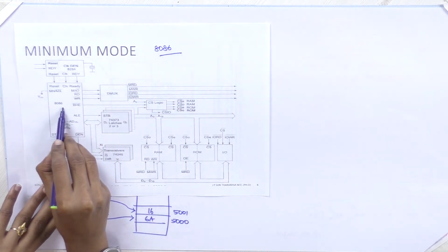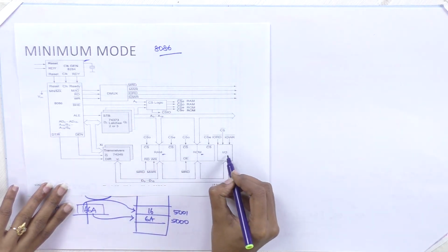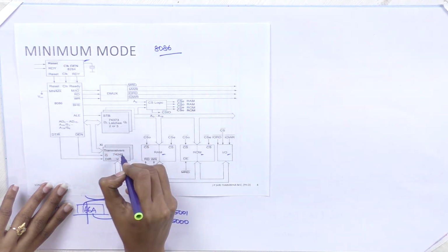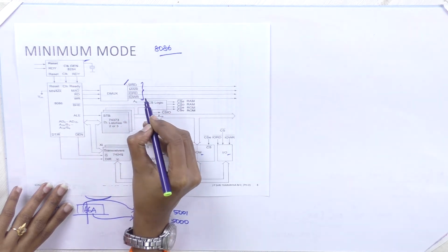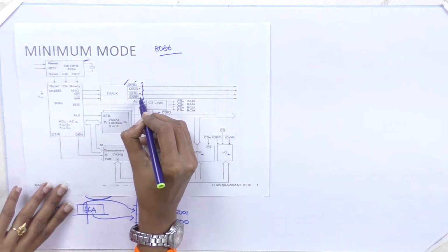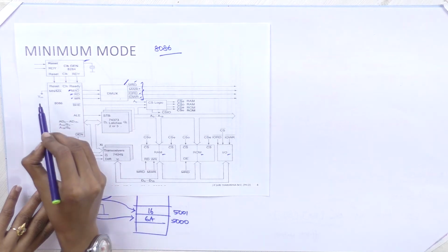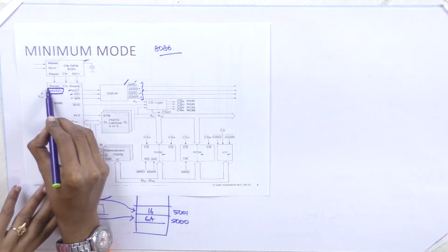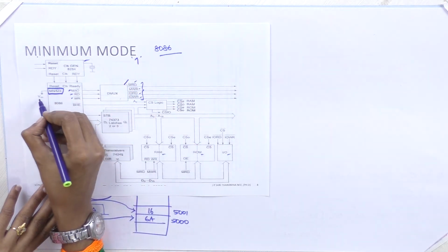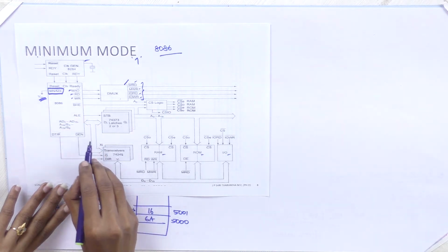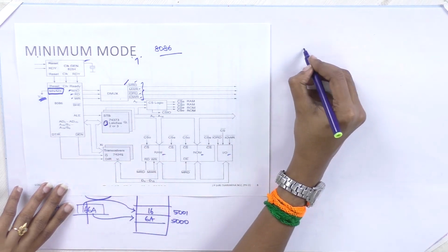Here you have your microprocessor, this is your oscillator circuit, and this is your memory, RAM, ROM, and then your IO devices, and this is a latch and transceiver, and this is a demultiplexer, fine. This demultiplexer will generate the control signals whether you are performing memory read, memory write, IO read, IO write. For this demultiplexer, your input lines are IO/M bar, read bar, write bar. This pin number 33 will decide whether the processor is in minimum or maximum mode. For minimum mode, I am supposed to give the value 1, so this pin is connected to VCC, fine. This is our D latch.